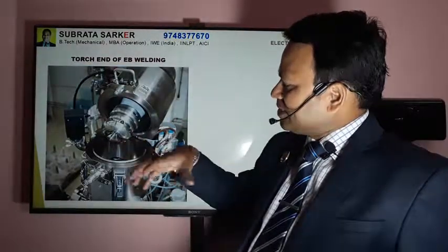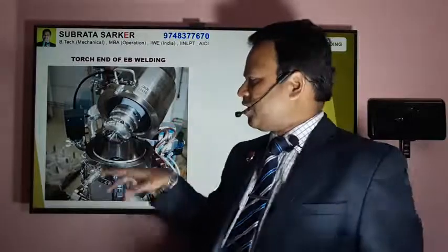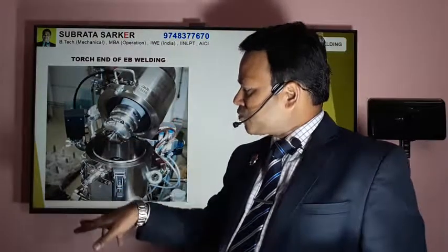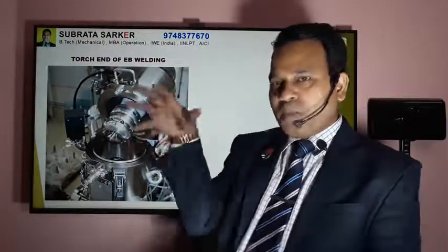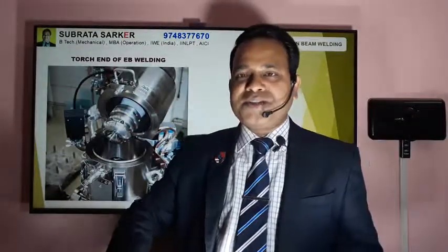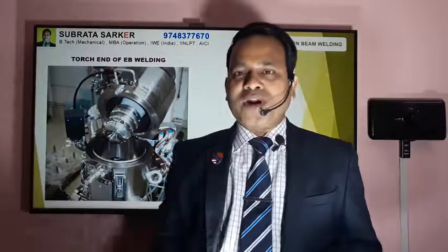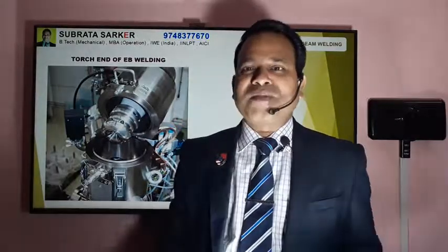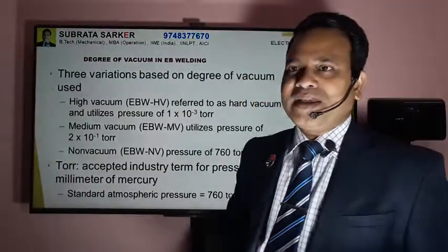And this is the detail of the beam head. The electron beam comes out from this area. Right now it is in the open position, so it will be closed down, and then the beam will give its energy to the workpiece, heat-strike the workpiece, and the workpiece will be welded automatically at that time.